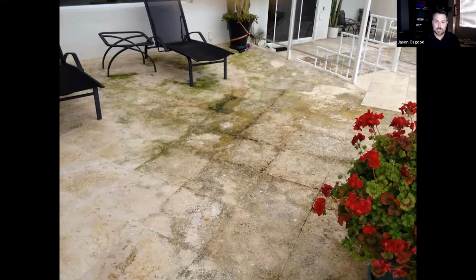The water runs into this spot, drains down in between the pavers, and just sits there over time because without the proper pitch on the base, the water has nowhere to run. The water has nowhere to go, and it just gets saturated and just sits there. Mold will grow. Keep this in mind. We don't mine this material with mold already in it. The mold and the mildew that grows on the deck is because the area stays moist, because the base stays wet.